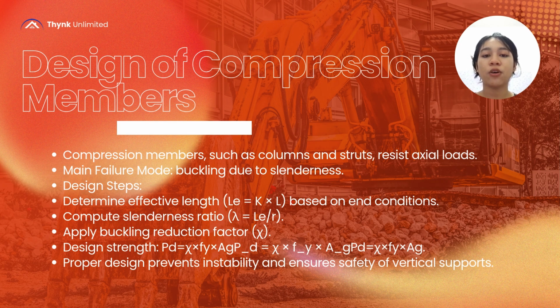Now we move on to the design of compression members. Compression members like columns and struts carry axial compressive load, and the main failure mode is buckling. The design steps are: calculate the effective length using LE = K multiplied by L, which means we multiply the K factor by the actual length L.